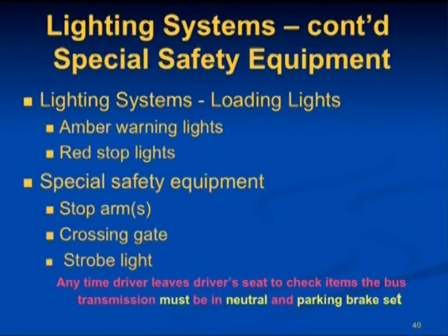Looking at the lighting systems and the special equipment. These lights and special equipment are provided as safety features to protect students while loading or unloading on the highway. The loading lights are activated by the driver with a manual switch which first activates the amber warning lights on the front and the rear of the bus. They flash alternately and can be checked standing in your stairwell or sometimes with crossover mirrors.